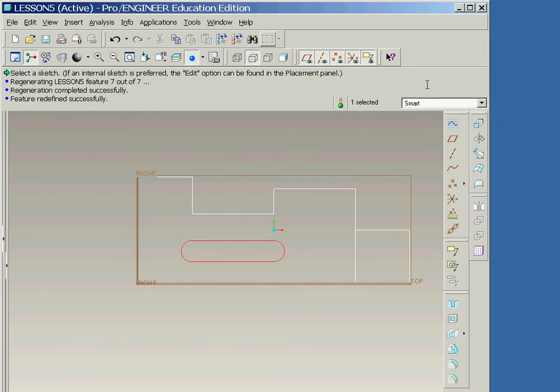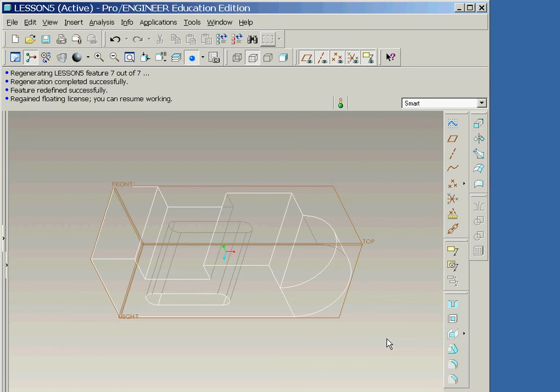Our next task will be to change one of the parent-child relationships of the inside cut. The top cut feature is the parent of the inside cut feature because of several different references that the inside cut makes to the top cut. Our goal is to eventually remove all of these dependent relationships.